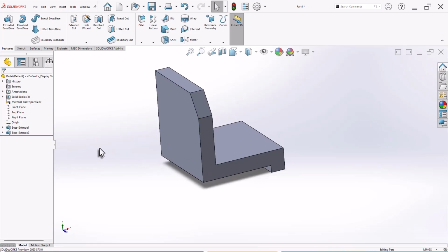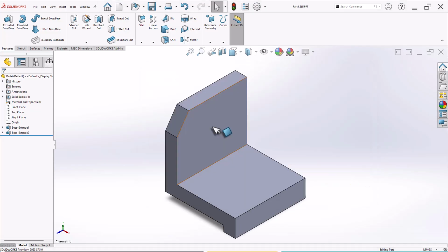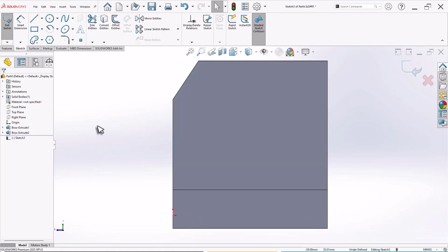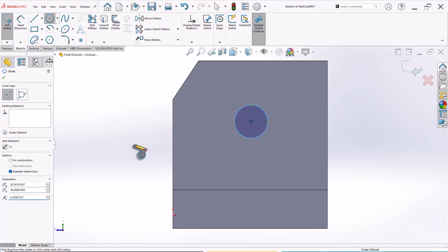Now press Ctrl 7 or save the exercise. Now the only remaining part is the circular cylinder. So select the surface because that is going to be our sketching plane, right? Again, let me click outside, select once again and choose sketch. Now right click and move left side, because I have added the circle tool on the left side of a mouse gesture. So draw the circle.